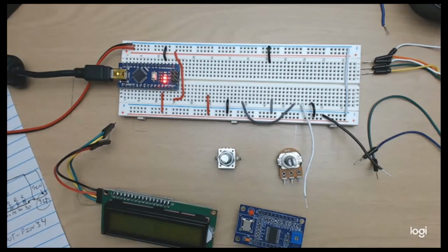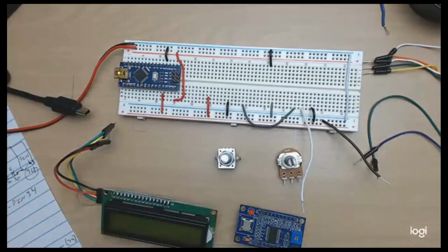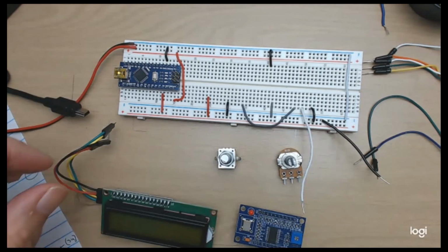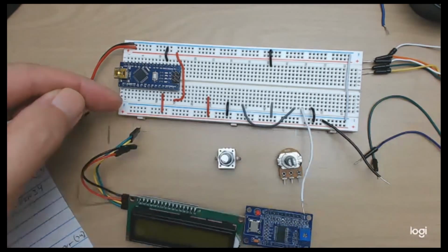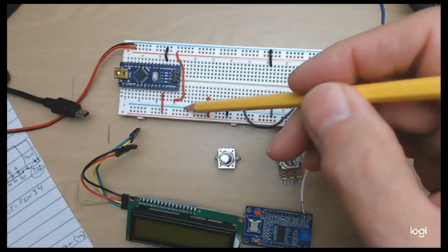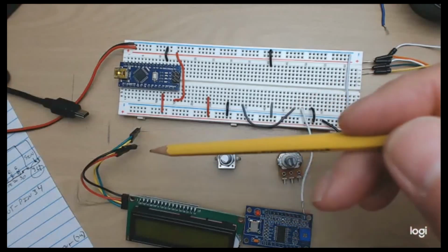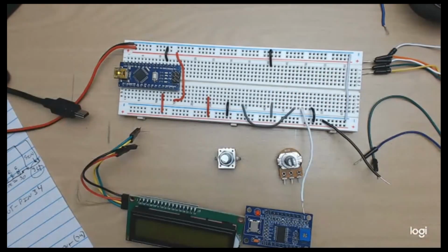All right. So what I need to do next is I want to hook up the display, and the next thing I want to do is see what the display does. So I'm going to unplug the USB port, and remember I said the display is only 4 wires. It's got a positive and a negative, and I've got my +5 rail here, and I've got my ground rail here. So that's really easy. And then I've got my serial clock and serial data lines, and those are the green and the yellow wires that come off of the back of the display.